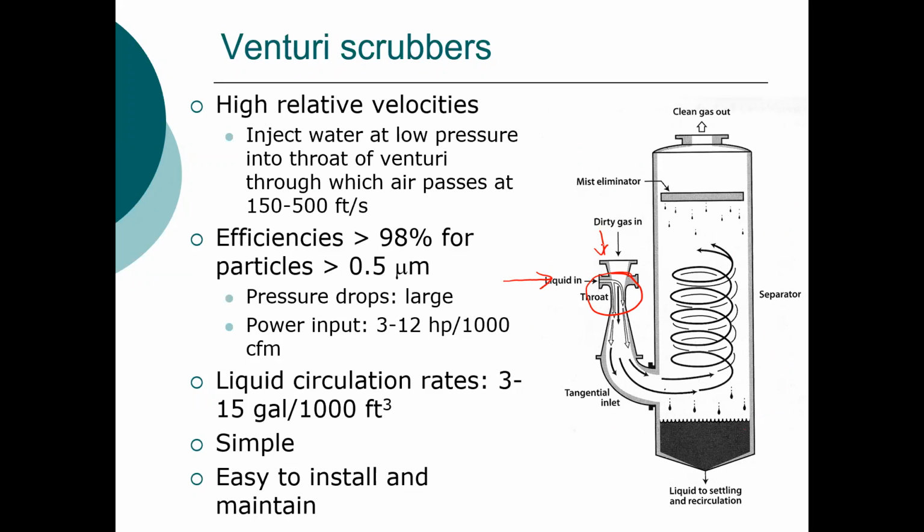The water and gas flow through that Venturi, and the negative pressure actually pulls the gas in, or the decrease in pressure. So typically here, efficiency is greater than about 98%. You want to operate these with relatively small particles, because you've got to ensure that you don't have clogging at that throat. You're relying on the Venturi rather than a pump.